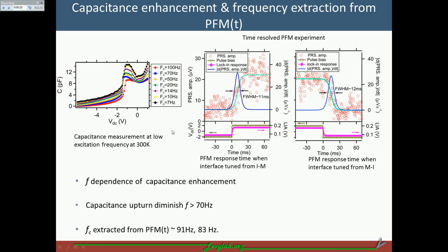Another thing we are trying to figure out is the capacitance enhancement phenomenon. We did capacitance measurements at different frequencies, and this frequency dependence of the capacitance enhancement was reproduced. To understand this, we did time-resolved piezo response measurements by switching the DC bias between positive 2 volts and negative 2 volts.